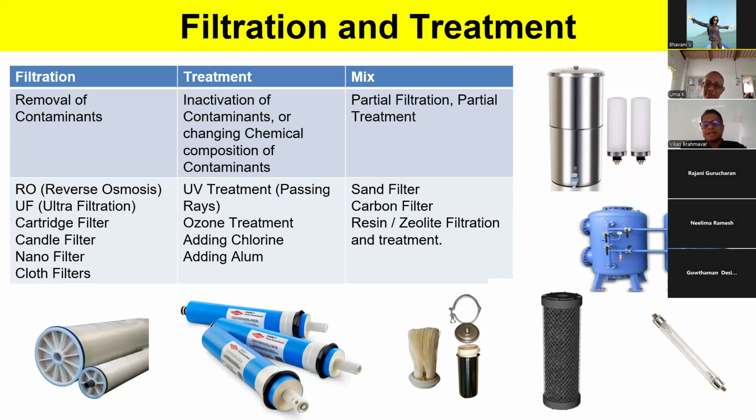We are always hesitant. Even for the Biome Academy project, we're so hesitant to add chlorine. It's way below the limit for disinfection, but it always needs to be added in the right quantity. However, Kaveri water, when you open your sump, will have a lot of chlorine in it. So chlorine, alum, all of these need to be added carefully based on how much is needed. General chlorine level is less than 1 ppm, 1 milligram per liter is what people have to add. Anything more than that, you will have a chlorine smell. Swimming pools maintain 1.2 to 1.5 ppm.